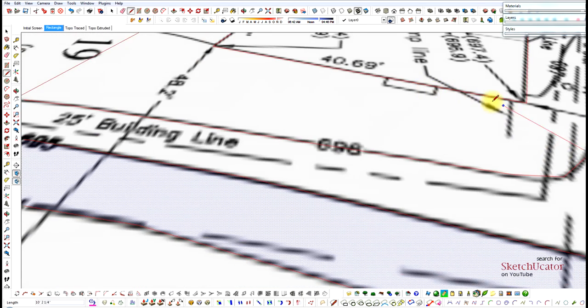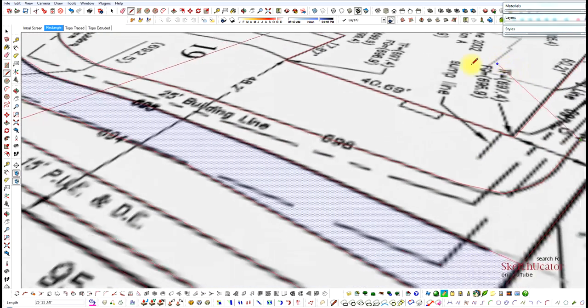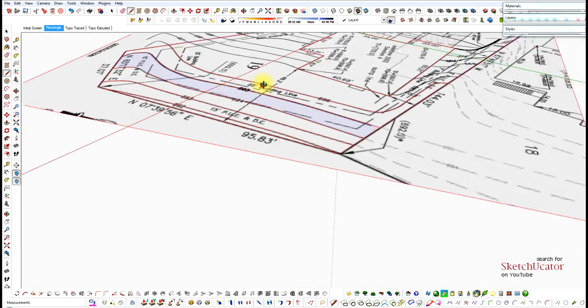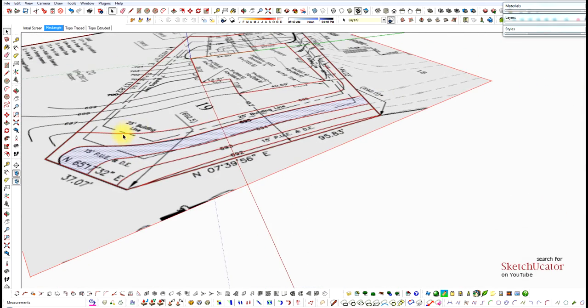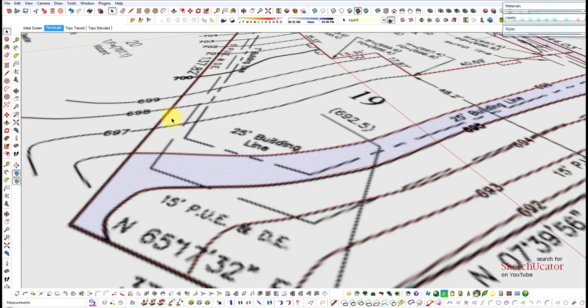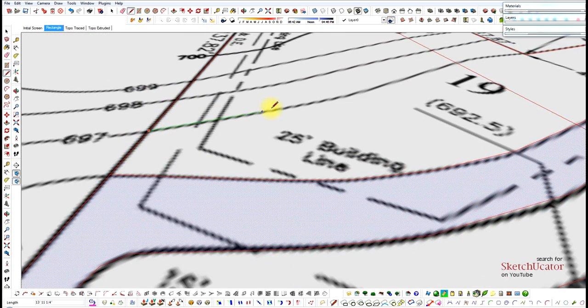So we go on around the whole building and do the same thing. There's a little bit of topography in this, so it'll take a little bit of time. But again, in the end, it'll be of value. I like to check these as I go, make sure I actually have cut the face. It's kind of easy to find yourself getting off that face. Make sure it does say on face as you do this.